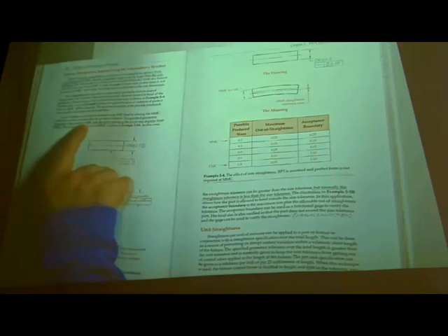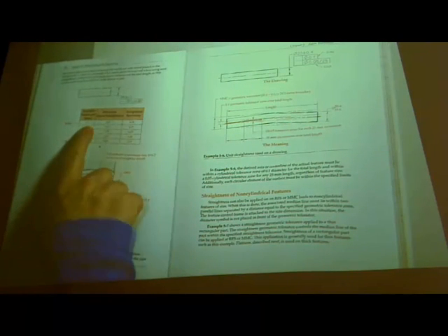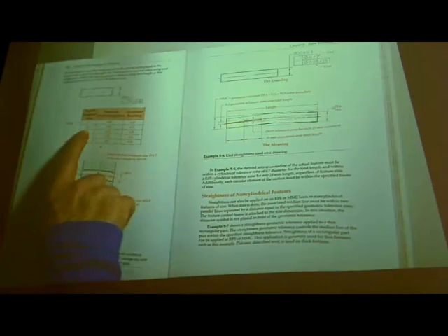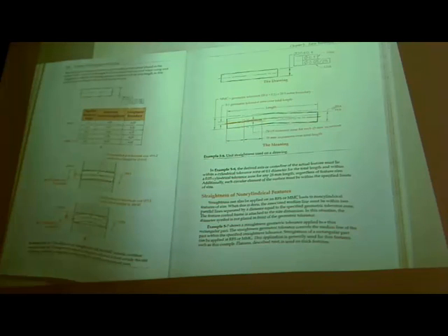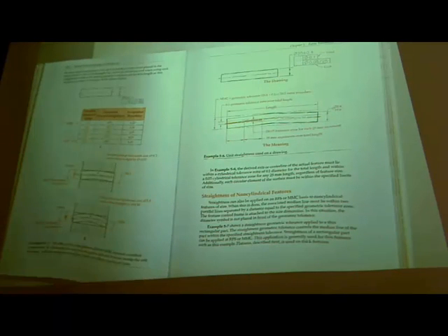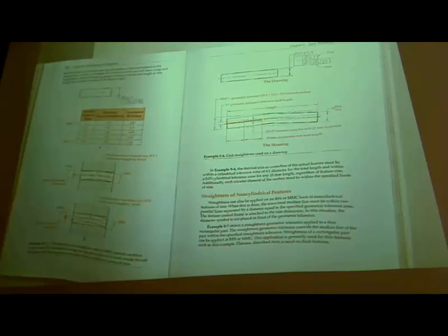So axis straightness can also be applied on an MMC basis, and we see that in this chart where we say at max material condition, okay, we need to hold maximum amount of straightness. Then as it departs from MMC, we're allowed to increase. Wow. Man, this thing can turn into a horseshoe. You know, 0.45, half of a millimeter almost. So they've put this in here this way to show you the extreme that you could run into.